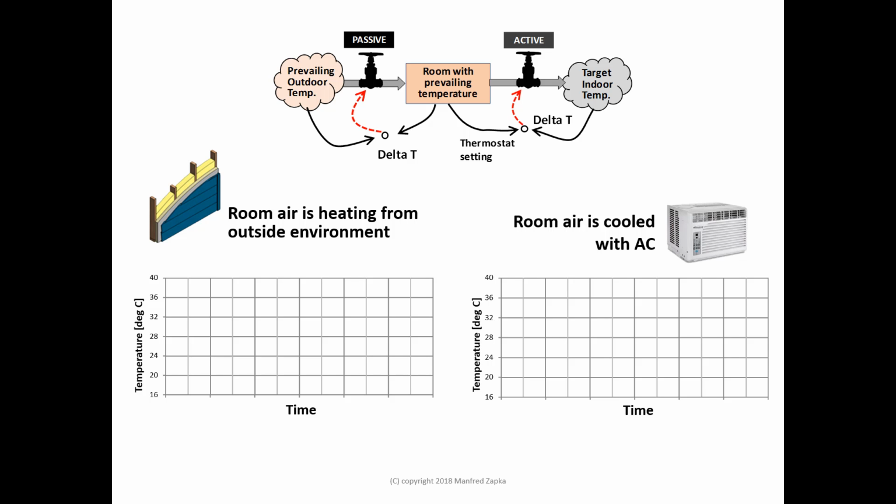This image illustrates the thermal dynamics of the two balancing loops. The left diagram shows the dynamics of the room temperature acquiring heat from the outside. With colder indoor and warmer outdoor temperatures, the heat that flows through the wall from the outside heats up the indoor space.